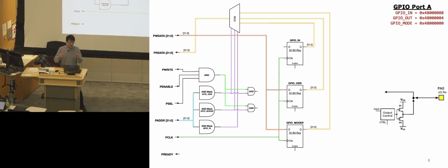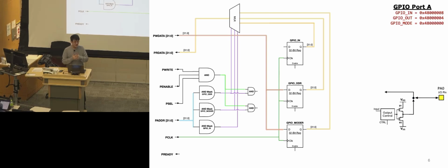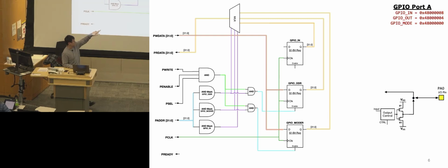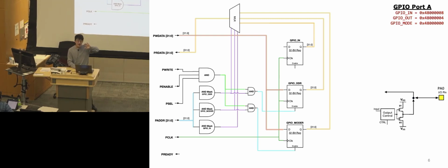Remember from MMIO, all the registers are essentially part of the memory of the entire system. So that address tells exactly which address a read or write instruction is targeting. Okay, so that's why there is an additional AND gate here for those signals before they connect to the enable. Okay, I hope that part is clear. Any questions on that part?